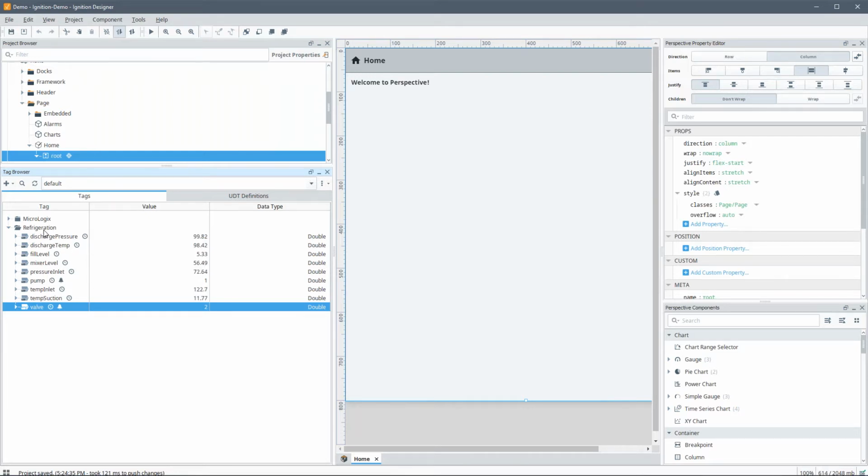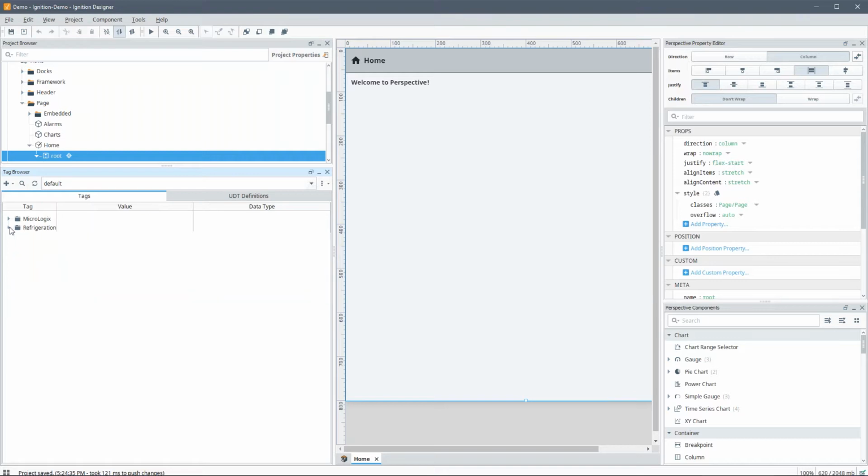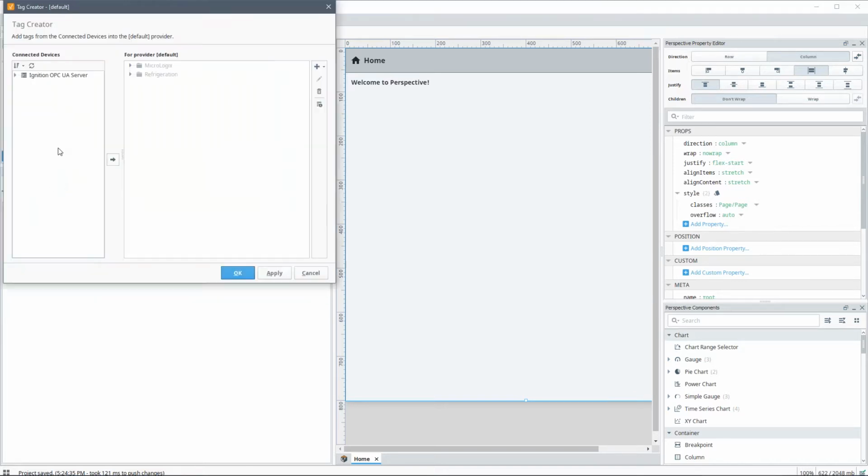Now the tags we built so far are just straight tags from PLCs. It's possible that we can actually leverage UDTs and instances, where we can build objects and use those objects and have them defined in one place. And that's what my ControlLogix PLC has, that notion. If I look at the CompactLogix, if I expand that, I've got tanks in here.